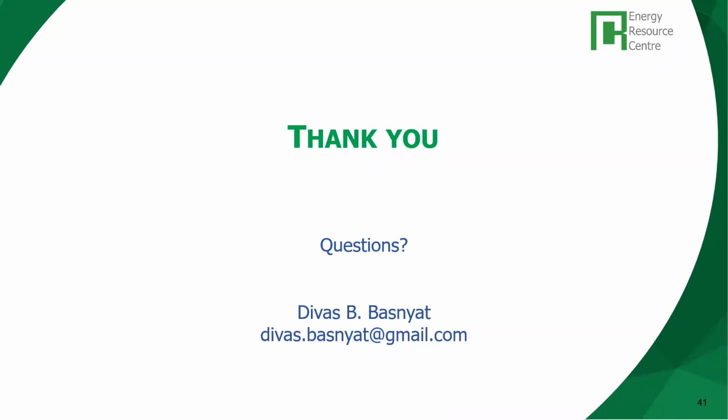You have to do a hydrological study, a topographical survey, a geological mapping survey, a socioeconomic, social and environmental study, and of course, the technical survey. So a mini micro hydro can be done within 1 year, but as the size increases, it normally takes 1 or 2 years for slightly bigger projects.